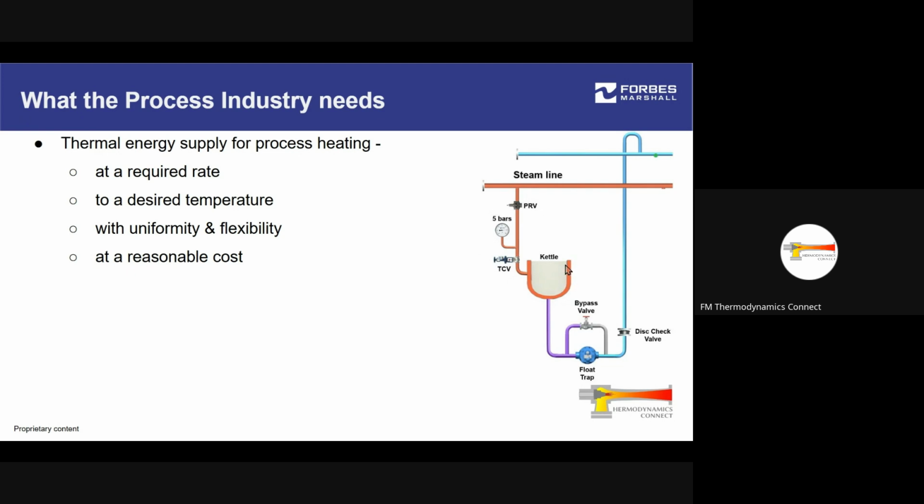If steam is entering into this segment, depending on what the pressure is, steam will have a saturation temperature because it is a two-phase system. You have a specific pressure, and with respect to that, you will have a specific temperature. But that temperature will be maintained uniform throughout the system. That's key to understand. So the heating has to be at a specific uniform temperature everywhere.